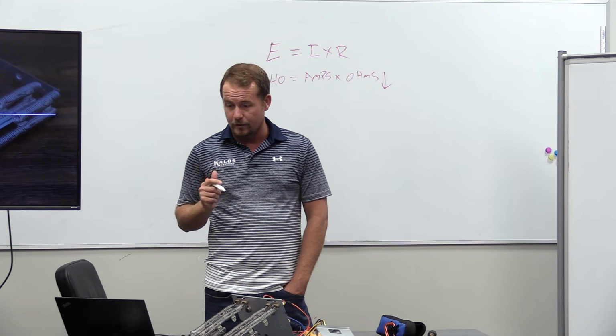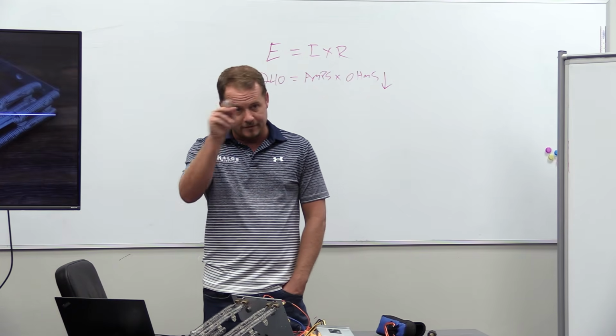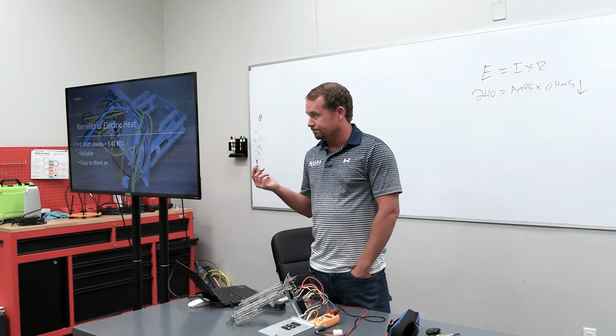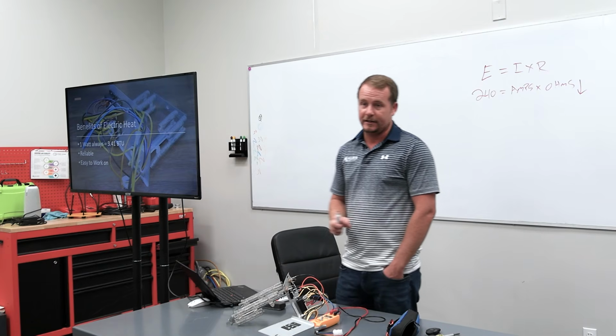Make sense? So it's important when you install heat strips, one of the most important things is that you don't short them out. You don't short them out to the casing around it. You don't short them out to each other. Pretty obvious. You will run into cases where things will lay across here just in the installation process.